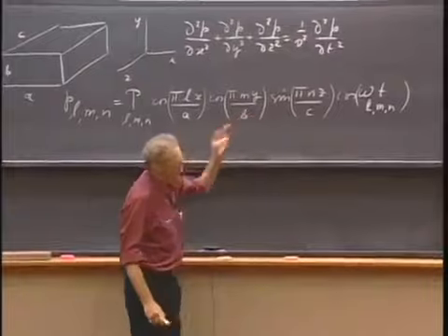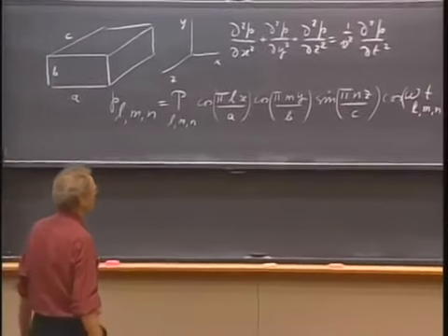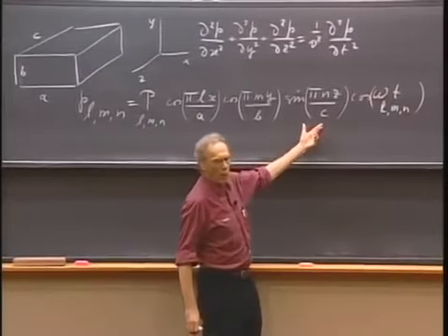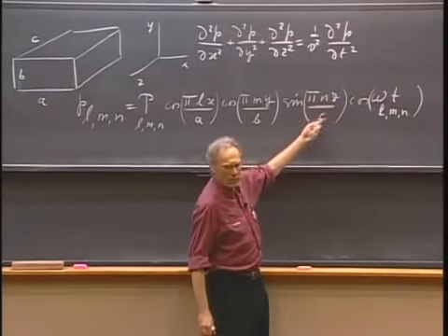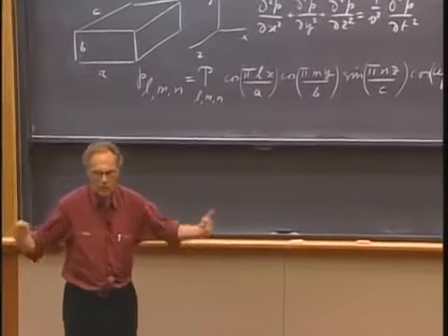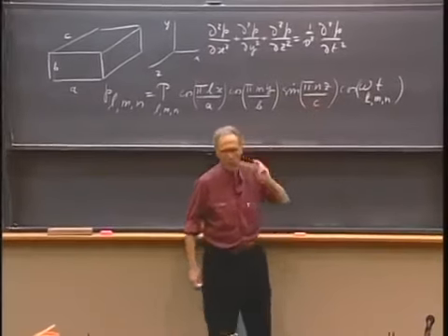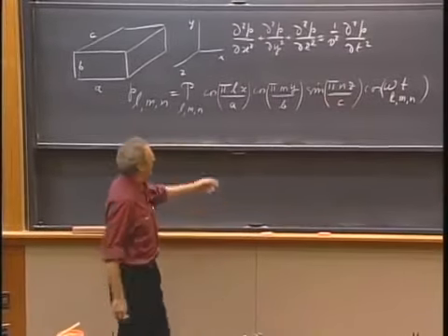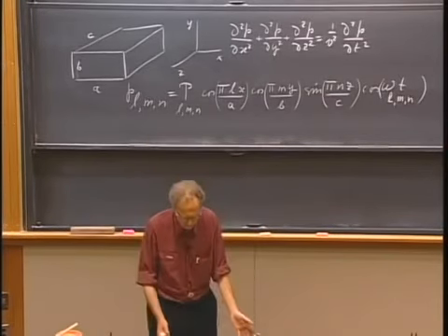And so you see, when you look there, convince yourself that you meet all the boundary conditions. This is the one that is the open end. That means if you substitute z equals 0, this one will make it 0. That's where you have the pressure node, where it's connected with the universe. No pressure can build up. But if you substitute in here z equals c, you also get 0. And you get the antinodes here. So this is a solution that immediately presents itself.